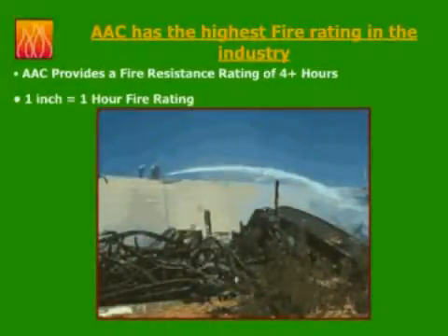This warehouse was a metal building with structural steel components. The warehouse had chemical items stored, which by a fire developed a temperature of up to 2000 degrees Fahrenheit. This is a temperature where steel loses its structural value and starts to deform. AAC can withstand an outstanding 2190 degrees, and this more than 100 hours. Let me show you personally how this works.